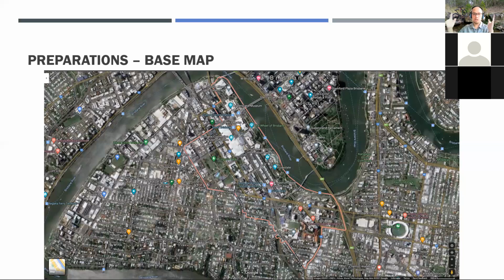So if you have a bigger area, you get smaller scales, 1 to 100, 1 to 200, 1 to 1,000, and so on. But with a smaller size or a smaller scope, you get a larger scale base map, 1 to 20, 1 to 10, and so on. Although I don't think 1 to 20 is a scale commonly used, even in architecture and interior design, but for site planning, I don't think you go down to the tens. Anyways.